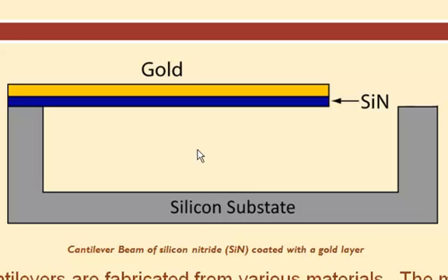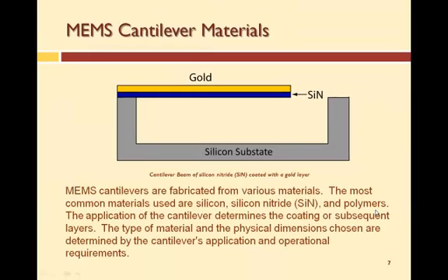So we can use anisotropic etching. For example, the potassium hydroxide, which we talked about in the crystallography unit. Right? That certain type of etchant will follow the crystal planes. So you can etch underneath something that doesn't etch in potassium hydroxide, for example, gold and silicon nitride. So you can make these kind of structures. Okay? People have made cantilevers out of just about any material you can think of.